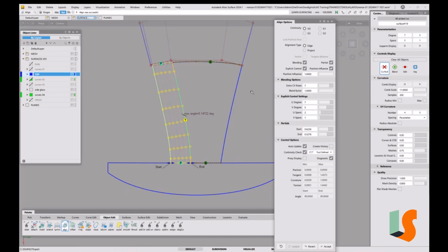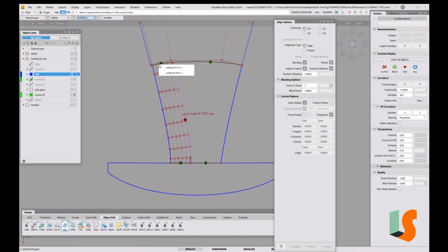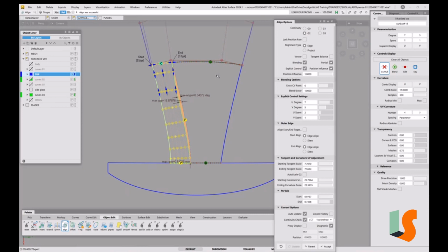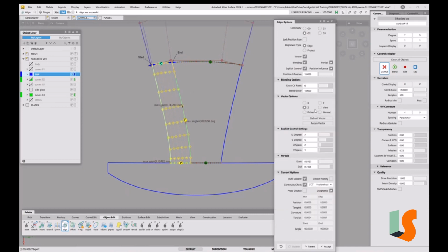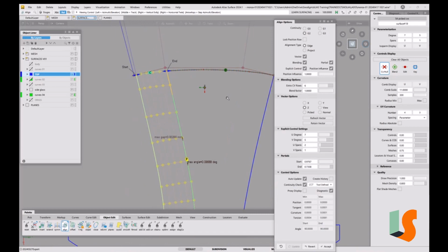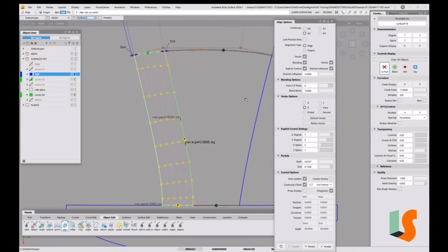Now, what I want to do is go in there and put curvature on. I'm going to do that into that edge. Need vector on. I don't want these moving in that direction. Notice when I was in G0, it didn't matter that I didn't have a vector on, it wasn't important. This is taking us far too far across here because I've got G2 on, it's affecting that row and that row, but then blend on top of that is trying to do 6 rows, 1, 2, 3, 4, 5, 6. So it's screwing up position match on that end.